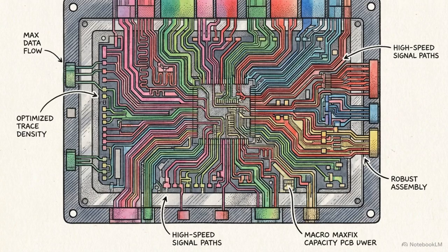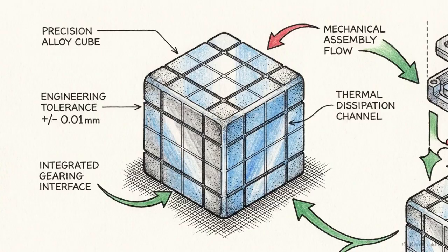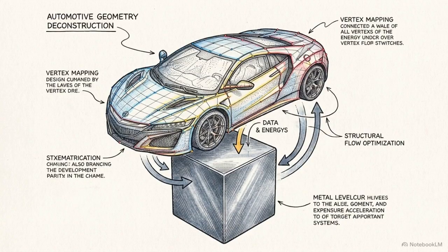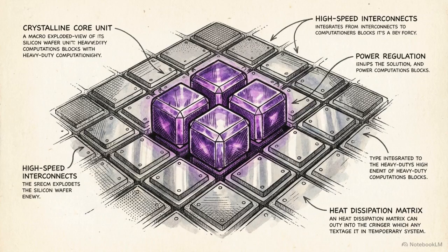pipeline with ready warps. Traditional math within the SM is handled by CUDA cores. These units are versatile, handling 32-bit arithmetic for general computing and 3D graphics. Deep learning, however, is driven by a single repetitive operation: matrix multiply and accumulate. Starting with the Volta generation, NVIDIA began a fundamental architectural pivot. They reallocated silicon die space from general CUDA cores to specialized blocks called Tensor Cores. These units sacrifice logical flexibility to execute dense matrix math. By hardwiring these operations into the silicon, Tensor Cores process neural network layers at speeds far exceeding general-purpose units.